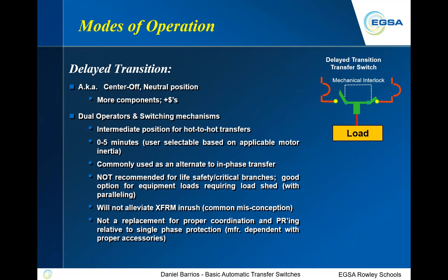Typically, you're not waiting 5 minutes. On wastewater and water treatment plants, they may delay a long time because it's not critical that they're back on within 10 seconds. A life safety switch, according to the National Electric Code, if it is an Article 700 installation, we'll touch on those, those life safety loads must be re-energized within 10 seconds.